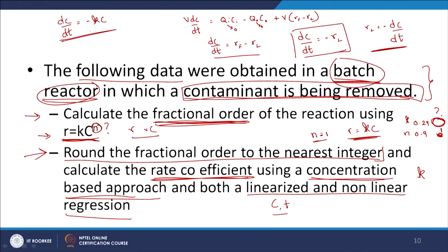And for this, we know that when I solve it from 0 to t, Ct is equal to C naught times e to the power of minus Kt. And why is that? Again, this is a batch reactor, and from my calculations I know that the rate of loss is equal to Kc, and first order.